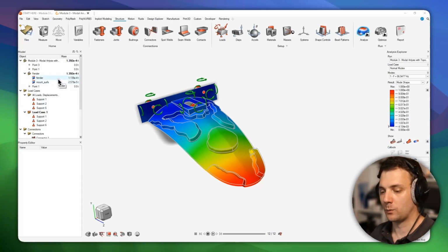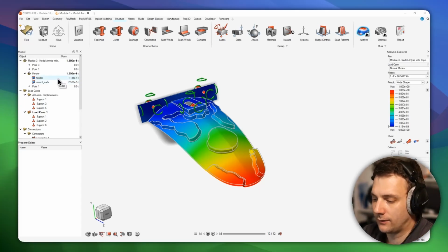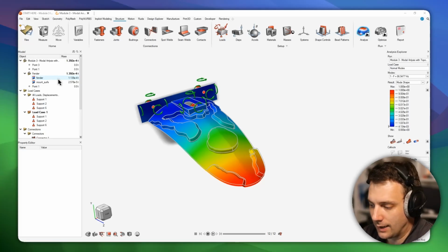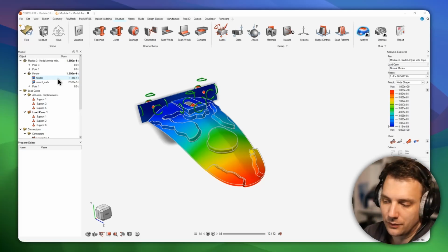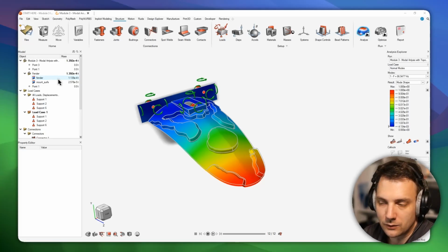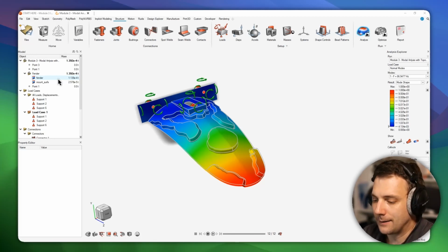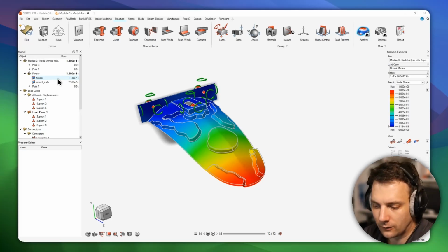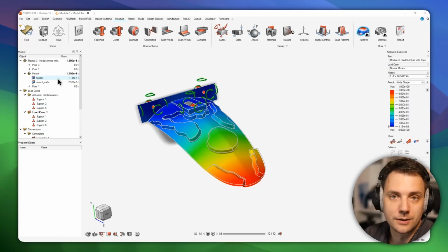So what you can take from that is topography optimization whenever you have a problem with frequencies. You can do the normal modes frequency analysis here in Inspire, and for sure in an industry context you would like to get a little bit more than just 10 modes. And yeah, we learned about connectors, material creation and assignment.